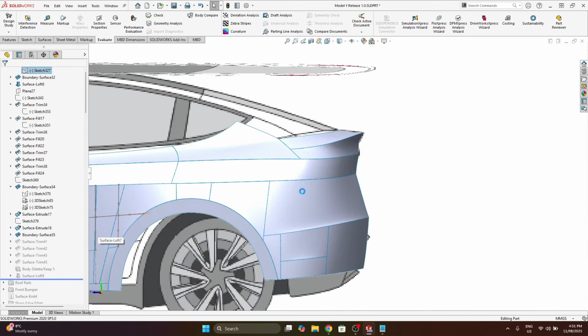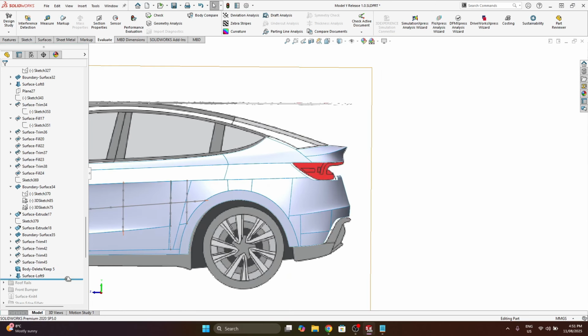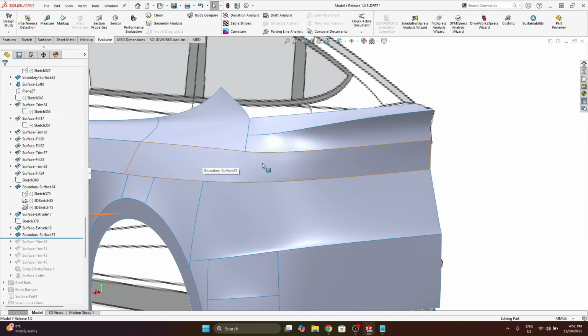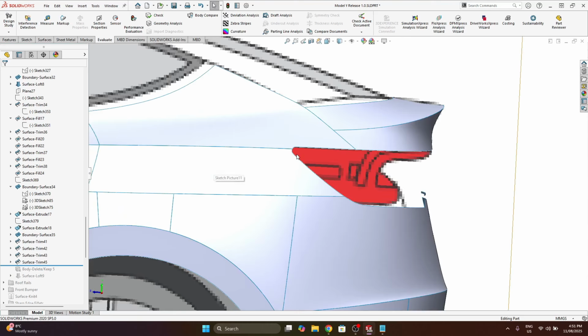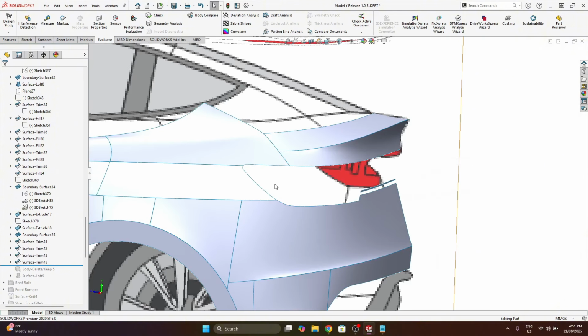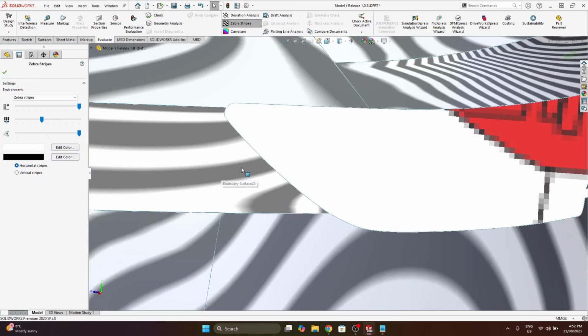So more or less continued the model using these approaches. In this case here, I've just trimmed away where I know the headlights will be. So just actually roll back there. Again, you get much better results if you build surfaces that are smooth and kind of long sweeping. And if you need complex boundaries, then you cut them out after. If I were to try build all these surfaces with this boundary for the headlight, I'm just not going to get good results. You can see here, if I turn on the zebra stripes, they're smooth running up to